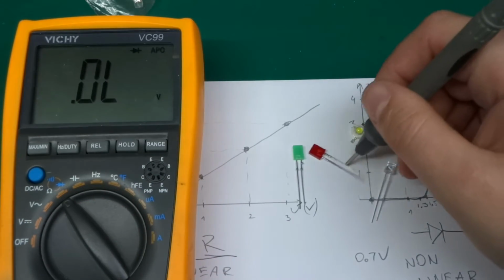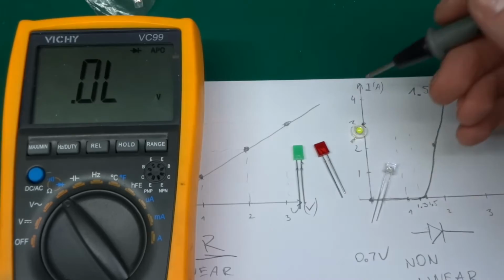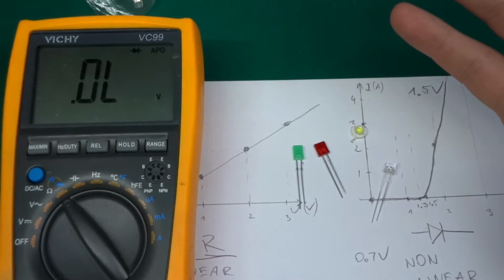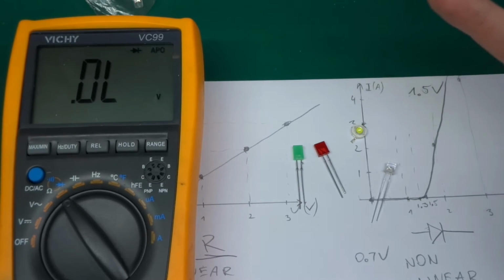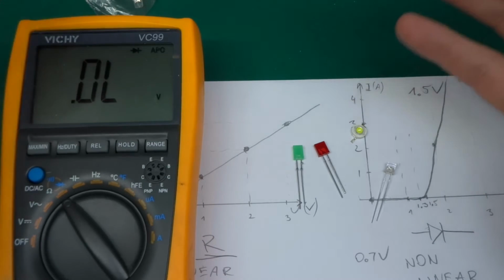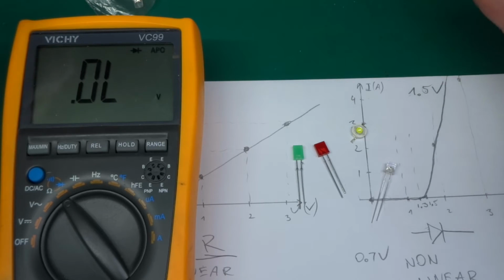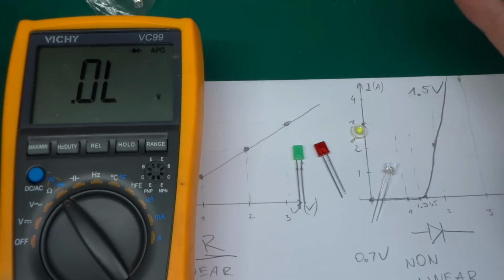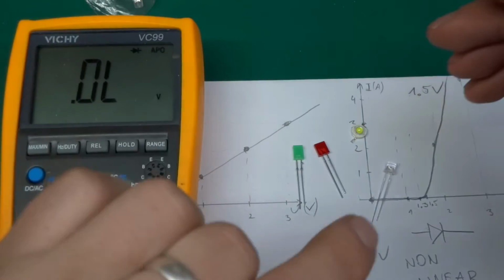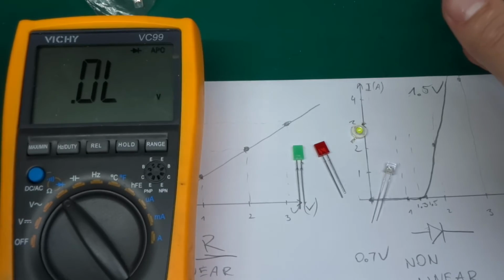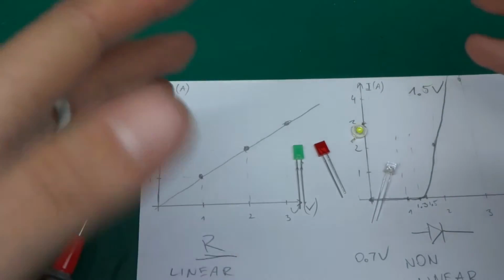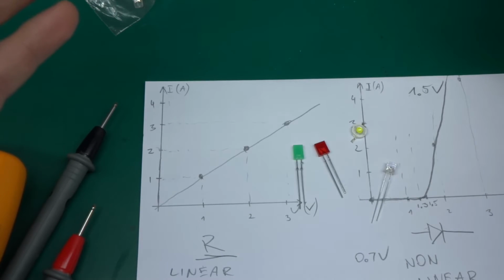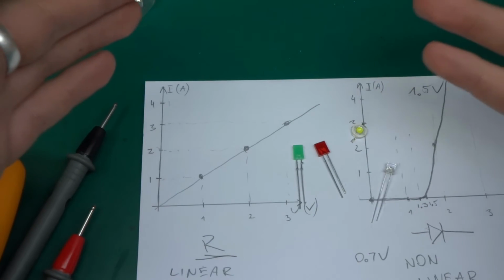Because those have a relatively low voltage drop, those will show up on the multimeter. The multimeter is meant to show mainly, as I said, low voltage drop diodes like rectifier diodes, for example, or Schottky diodes, to check if they're working, if they're broken, or if they conduct in both directions. That's the idea behind it, but it's not meant for LEDs. So how do you quickly check an LED? Well, as long as your LED is a low power LED, say under a watt, maybe even under 3 watts, you could do this trick.